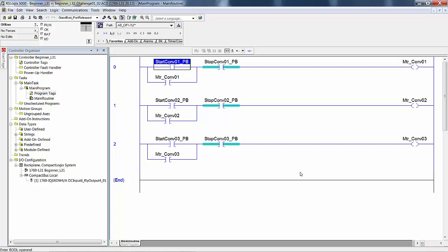Be very careful when you're messing around with tag names that you're conscious whether you're editing an existing tag because you want to give it a different name, not a new name, a different name. If you're working with a new tag, do not open the properties on an existing tag. Just type it in, then right-click, new, change whatever, and create.